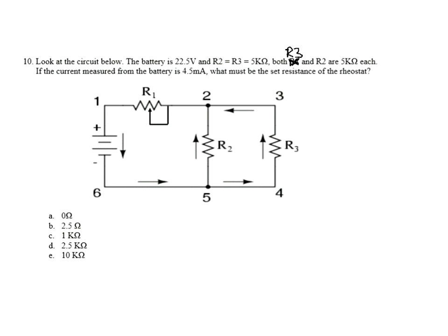Okay, so what is this? Let's see here. I apologize for that mistake. R2 and R3 are how many K each? Well, they're 5K each. Let's write that in. 5K. What is 5K in parallel with 5K? Well, we did that before. 5K in parallel with 5K would be 2.5K.